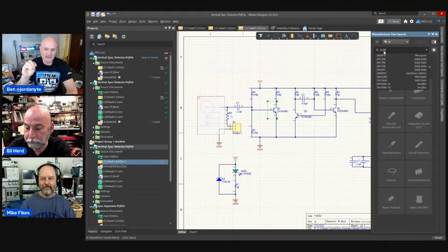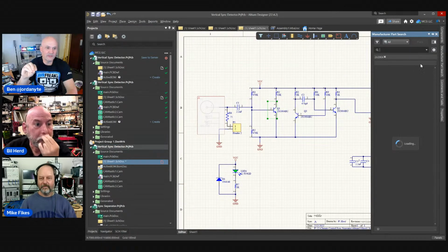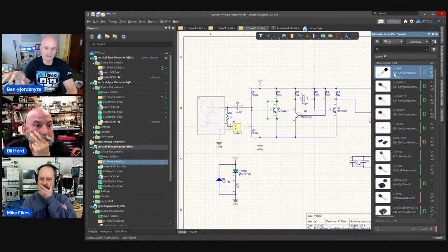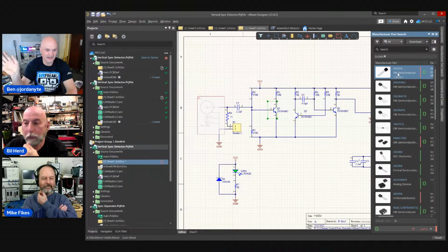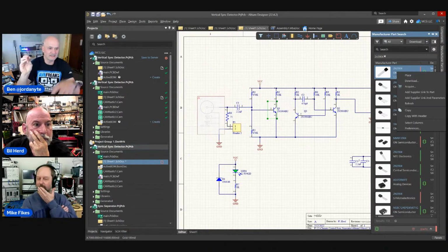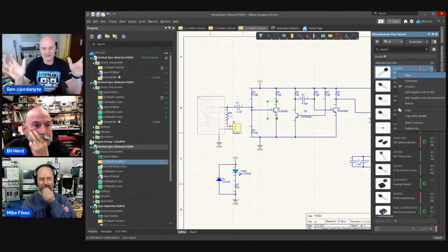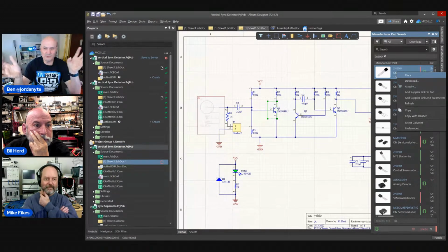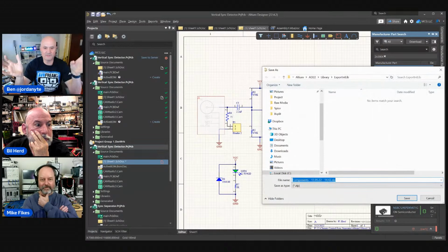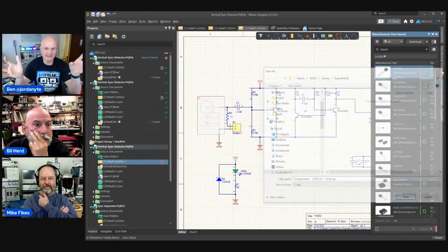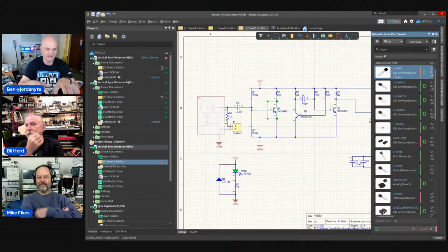There you can download all the old PCB libraries that used to come with Altium before they had any of this cloud stuff or any vaults or managed data. Altium Designer Summer 09 was the last version that shipped with about 200 or 300 megabytes worth of libraries you could install as standalone desktop libraries.